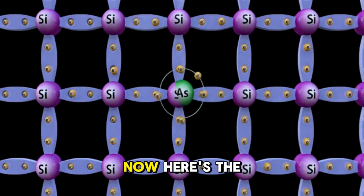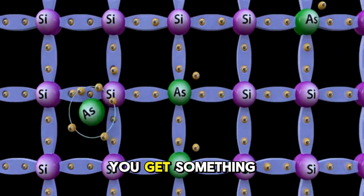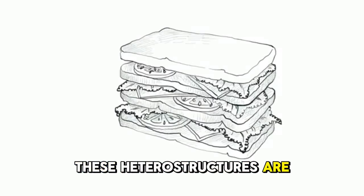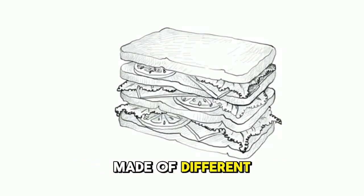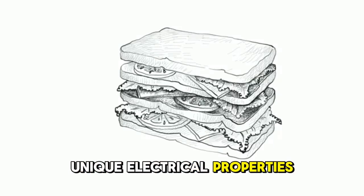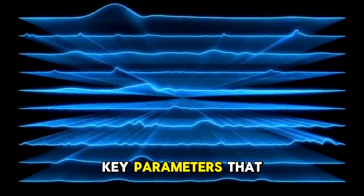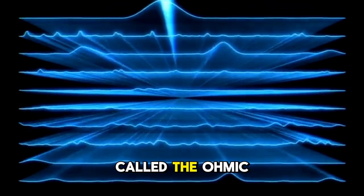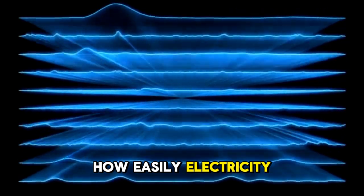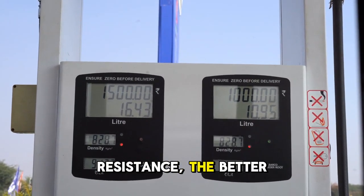Now here's the thing, when you stack different layers of materials in a semiconductor, you get something called a heterostructure. These heterostructures are like little sandwiches made of different kinds of materials, and they have unique electrical properties that depend on how well the layers are matched. One of the key parameters that affects this is called the ohmic contact resistance, which is basically how easily electricity can flow between different materials. The lower the resistance, the better.